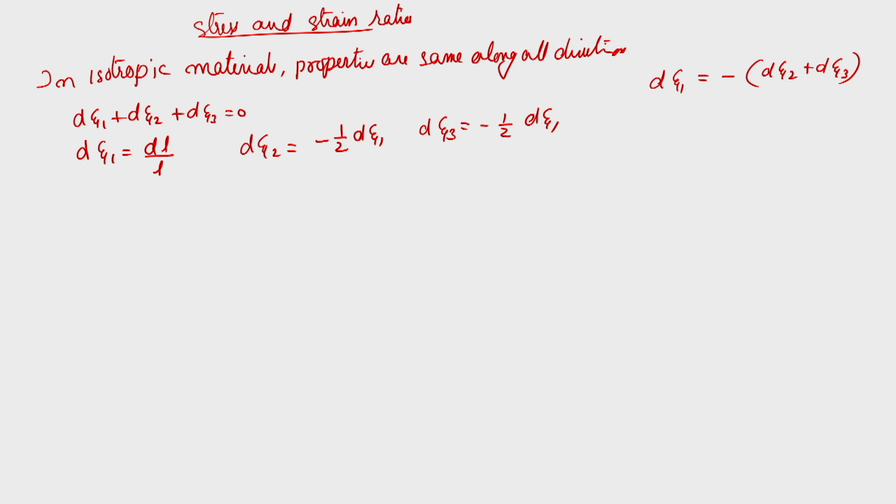So, what are the stresses and strains? If you look at it, sigma 1 is equal to P by A, where A is your cross sectional area, sigma 2 is equal to 0 and sigma 3 is equal to 0. I am telling this is for the uniaxial tensile test. For a uniaxial tensile test, that is the condition. So, you will find that these are the conditions.